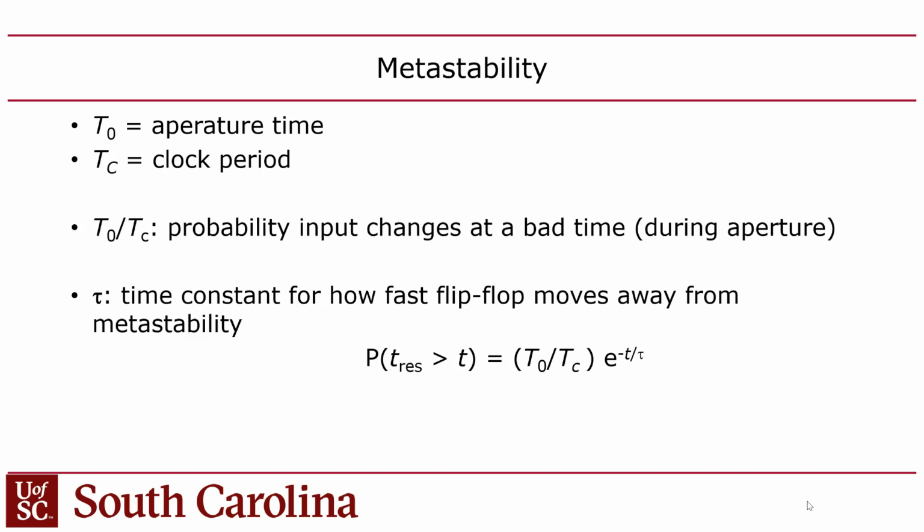Can you please explain, you said that PMOS transistors are weaker than NMOS. Why so? I don't get it. It's the mobility of the charge carriers in the P type are slower, and so you can make the PMOS bigger to try to compensate. But if you do that, it increases the resistance. I think it doesn't increase the resistance. It increases the capacitance. Capacitance, right?